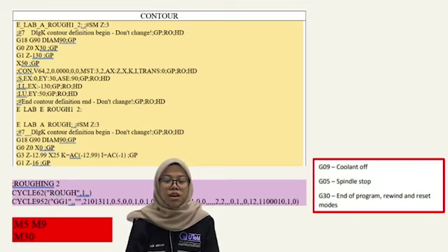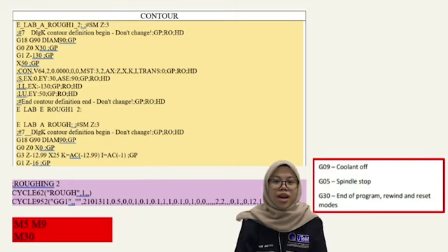And lastly, for the finishing, we changed to the finishing tool and then put the spindle speed and then insert the coding for the finishing process, and lastly, we put the tools back to the safety position so it's not going to collide with the workpiece, and we put M30 to end the program.